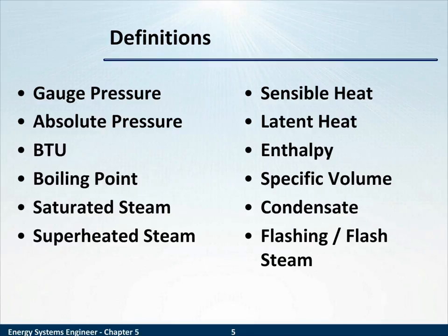Enthalpy, for our discussion, we will avoid the chemical engineering course in enthalpy and just call it the internal energy. When we say enthalpy, we mean the energy internal to the compound we're discussing. Specific volume, think of it in terms of density. It's indeed the reciprocal of density. It's 1 over the density. But when you think of specific volume, think of it as a measure of density. Units of specific volume would be, instead of pounds per cubic feet, cubic feet per pound. Instead of grams per cubic centimeter or kilograms per cubic meter, it would be cubic centimeters per gram or cubic meters per kilogram.